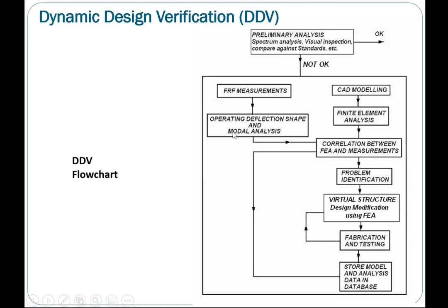Right, modal analysis will give us the set of natural frequencies, damping and mode shapes, telling us its dynamic behavior or dynamic characteristics of that particular machine. It will help us explain why it is vibrating in that particular way and why you have high vibrations. So these two can help us explain the dynamics of that particular machine. So ODS and modal analysis are combined with computational mechanics.